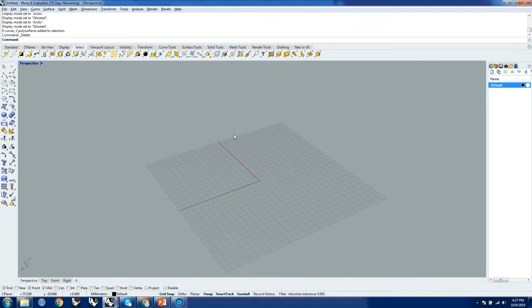Okay, and we also made some decisions on the fly while choosing which object snaps to turn on for different operations. For example, end snap was on while picking up some points on the edges or on the end points of the curves. We checked the point object snap on while we were making polylines on top of already existing points, and such.